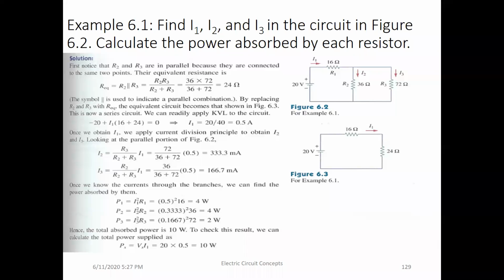There is a rule of thumb that when we determine the equivalent resistance and we have more than one resistor, it is good to start at the far end away from the voltage source. So don't start with R1. Don't combine R1 with R2 or with R3, because R1 is not connected to R2 in series, and R1 and R3 are not connected in series, nor in parallel. So the best way is always to start from this end here.